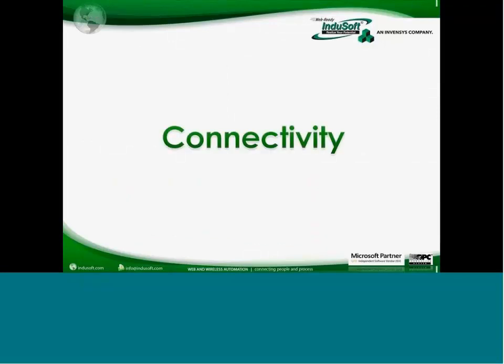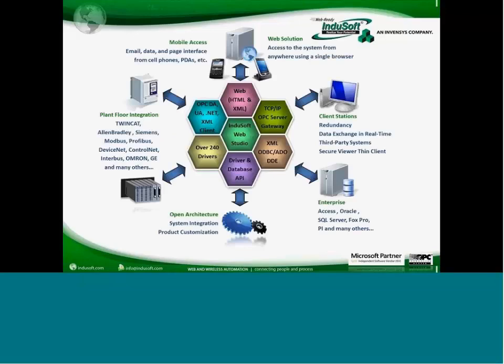So, a little bit about the connectivity options that you have with InduSoft Web Studio. I'm going to start here on this area where we first talk about the OPC options. We have all the flavors of OPC: OPC Classic, which used to be OPC DA, and we have the Unified Architecture client as well, UA. We have OPC .NET 3 and XML. So we have all the OPC options as part of the InduSoft offering.